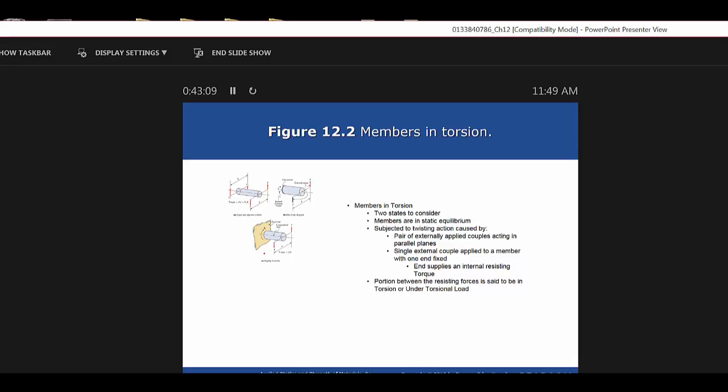Okay. So if we look at that, again, note that that's strictly pure shear stress. There's nothing pulling that shaft or compressing that shaft. It's strictly torque, if you will, from that perspective. There's no bending or direct tension or compression on that. The internal resistance to the slippage of the material or the deformation is known as torsional shear stress.